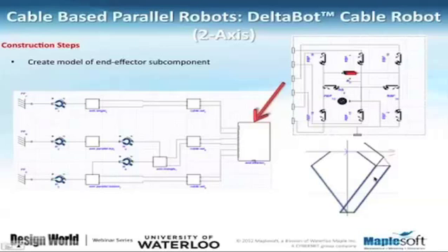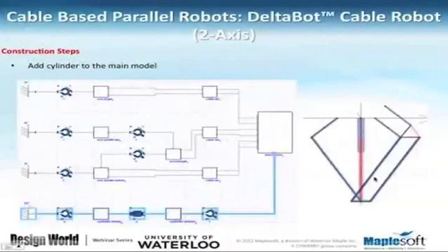and then the next step is obviously to add the cylinder. And for the cylinder, the design will be as simple as the other components that we discussed. So we start with another rigid or the frame, fixed frame, and then we add another revolute joint, and that revolute joint is in fact right on the top here.